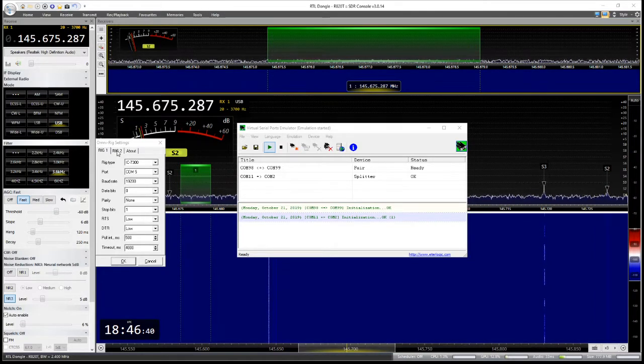All right. So I have mine set. Rig 1 is a 7300. I use that on HF. It allows 2 rigs. So this is what I have in here for the rig for the 857D. Take a good look at that. Now this COM port, this is where the baud rate is set, seems to work well. RTS high, DTR low. Everything else I leave alone.